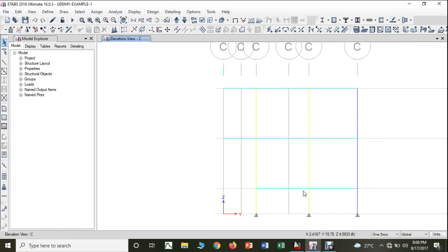And the second reason is we have to construct the wall here. To construct the wall, either we have to put the foundation here or we have to put the plinth beam. For these two reasons, we are putting the plinth beam. Since the plinth beam is resting on the soil, the load received on the plinth beam is much lower compared to this beam and this beam. The load received on roof beams is higher compared to the load received on the plinth beam.